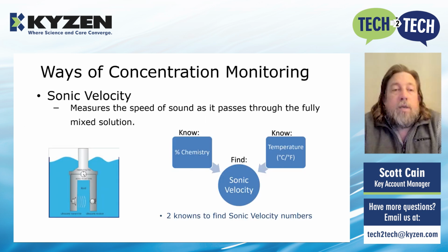Another way that we do this is by sonic velocity. And sonic velocity is the best way to dial in that concentration, to know what's going on. What that is doing is using sound waves to determine how much of each material should be within the concentration at that point. So it's not just testing the overall, it's testing the individual ingredients that are in there. And then we know what those sweet spots are, where the concentration is, what that sonic velocity should be. And so that'll read out on some of the options that we offer.